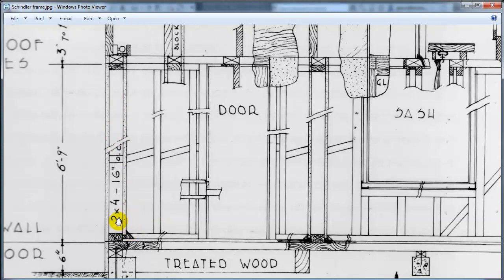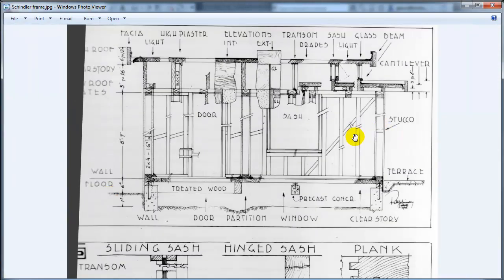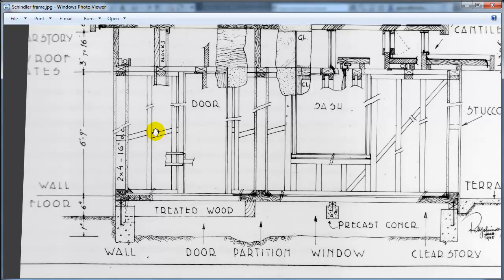It's the standard exterior wall, 2x4 studs at 16 inches on center. It's got some sort of stucco layer on the outside, I can see, and probably just plaster on the inside. These days we'd probably do stucco on the outside and maybe gypboard on the inside, but we'll model his system. We don't have dimensions.